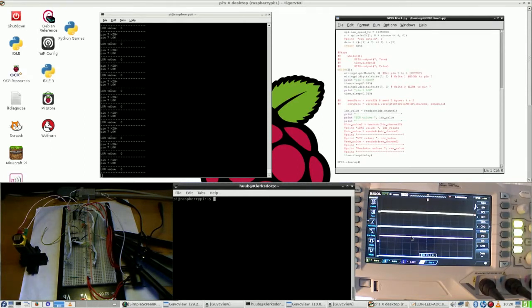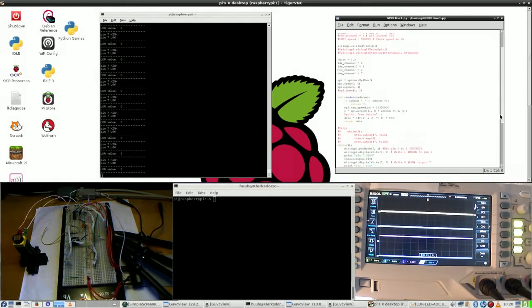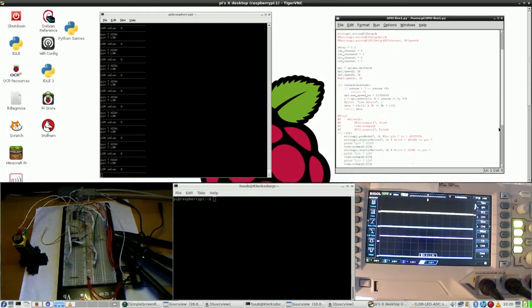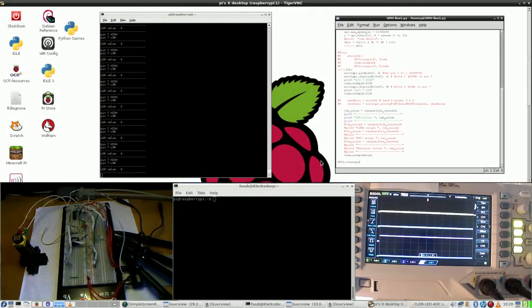What I don't like, by the way, is that I don't even have a chip select mechanism here. That is strange. I should have at least a pulse. So is the GPIO broken? I tested it last time, I think, and it didn't give anything.